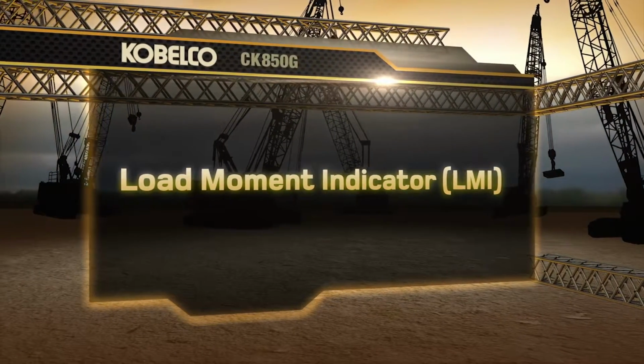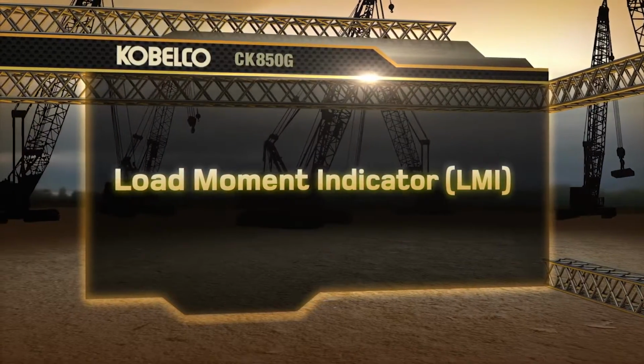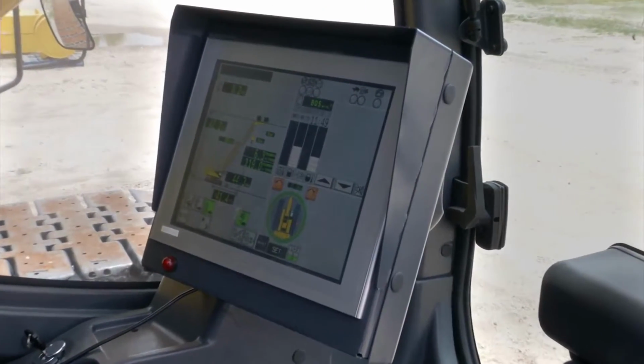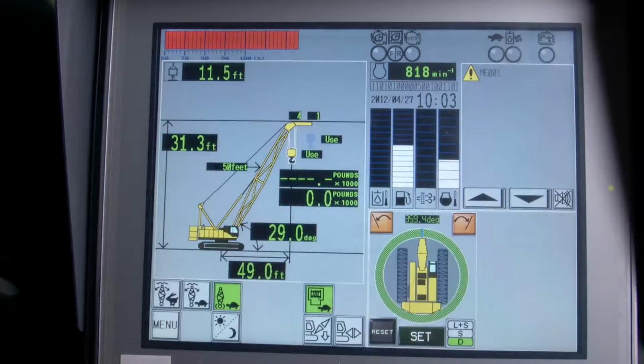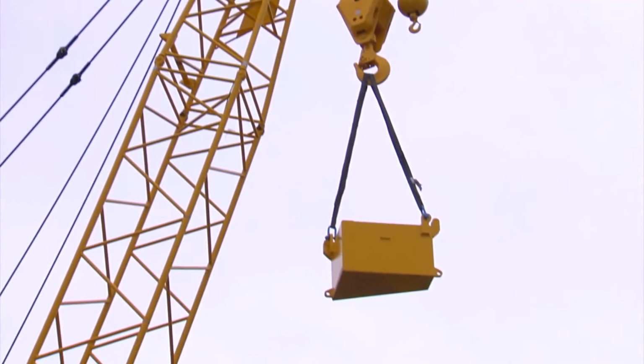In this section, we'll cover the Kobelco LMI Load Moment Indicator touchscreen monitor that is designed and built by Kobelco as an integral part of the crane's design. This system provides audio and visual signals as the load or the radius approaches maximum limits and stops crane functions when the limit is reached.